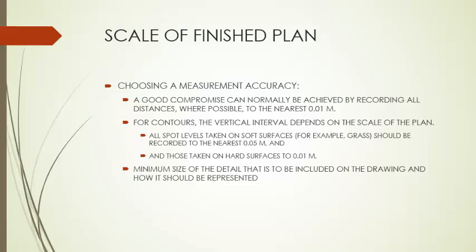In areas where there is insufficient detail at which spot levels can be taken, a grid of spot levels should be surveyed in the field and plotted on a plan. The size of the grid depends on the scale.